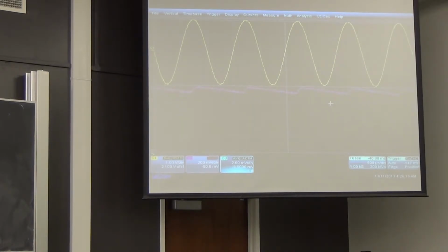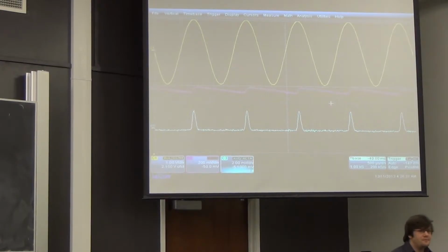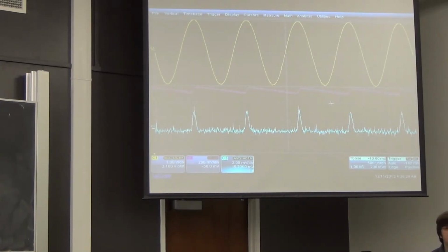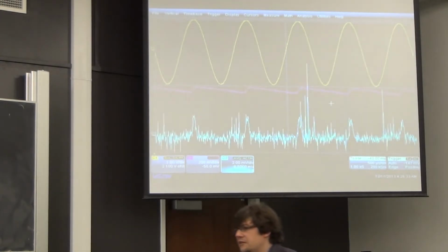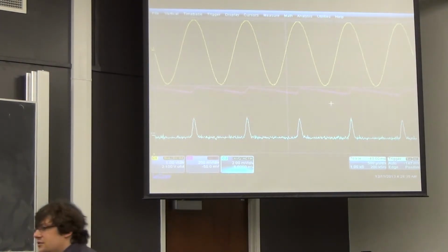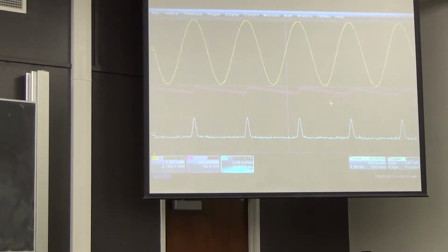So the magenta line is now very triangular, and the distance between the two peaks, or edges of the peak, in the cyan line is a bit closer together. If we went to a really high resistance, a couple of hundred kiloohms, the effect would be much more obvious. But the other thing to know, of course, is the area under that line has dropped somewhat because we're adding and removing less charge per cycle from the capacitor.